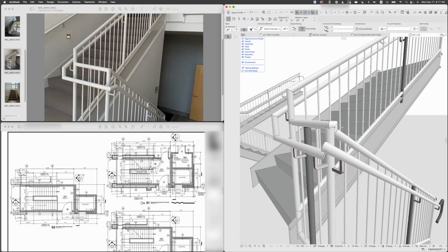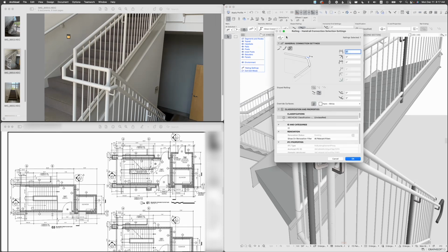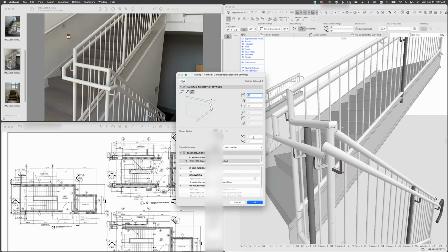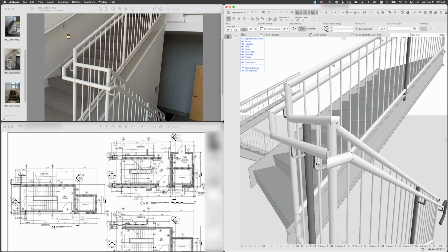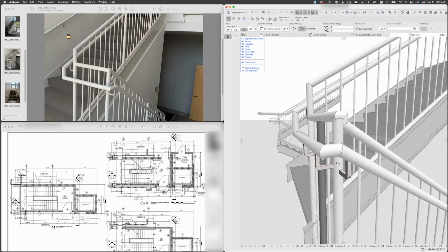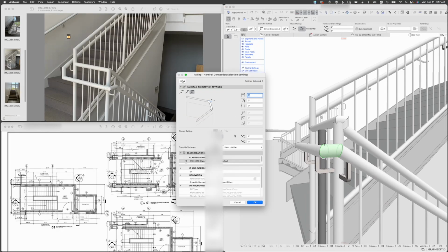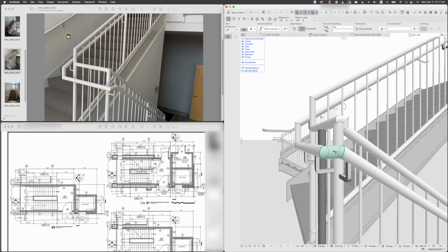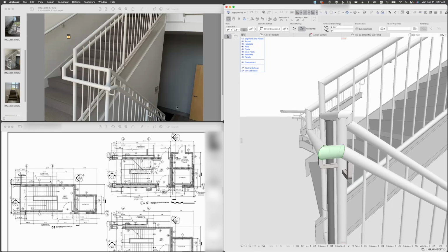So we need to go to the connection and make sure we have some number here, horizontal offset. I believe it was like 4 inches, or okay, not 4, maybe was it 2 inches? Yeah, almost. I think it was like 2 1/4. So I can type 2 1/4, and yes, it was exactly like what we see here.